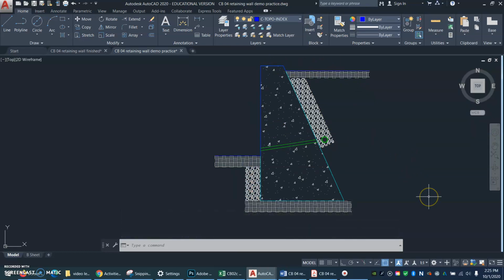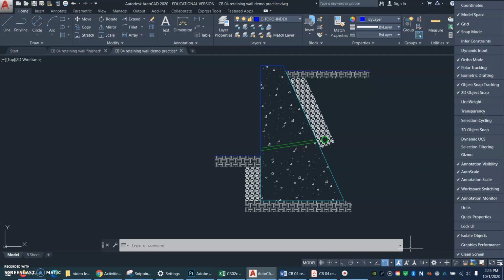And if I do one more tricky thing, I want to turn on the line weight doodad down here at the bottom. It's not there, so I'm going to click on this hamburger, this stack of menus, and I'm going to select from this menu of tools, I'm going to select line weight. Watch the taskbar add the thing.